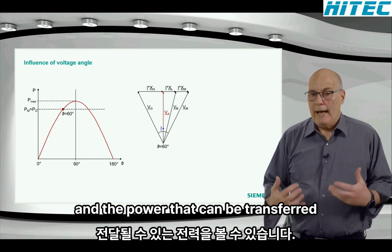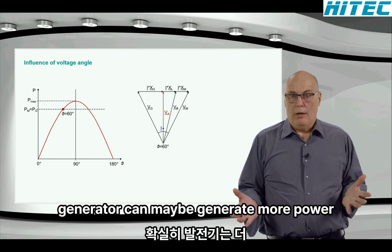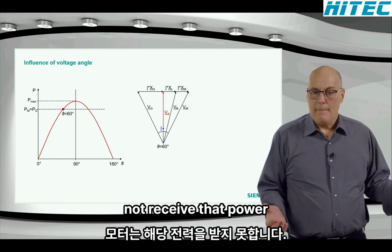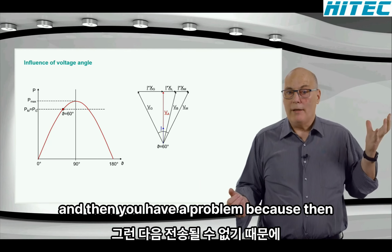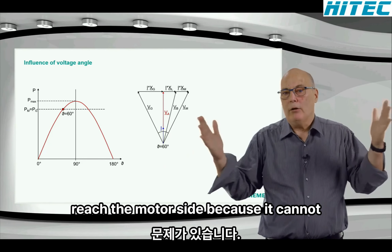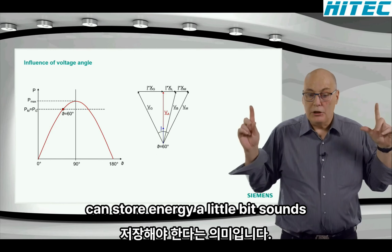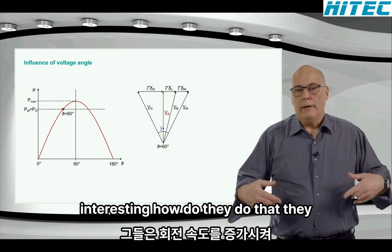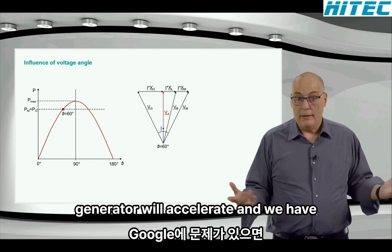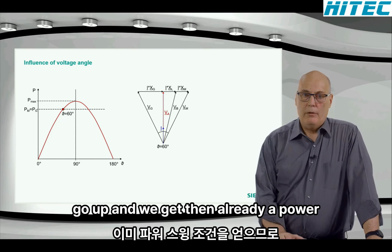This is an important thing: the power that can be transferred. Surely the generator can maybe generate more power, but the electrical system cannot transfer that power, so the motor does not receive it. Then you have a problem, because there is real energy at the generator side which does not reach the motor side. That means the generator needs to store that energy. Generators can store energy a little bit. How do they do that? They increase their rotational speed. They store it as rotational energy. The generator will accelerate, the frequency will go up, and we then already get a power swing condition.